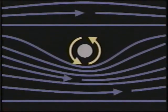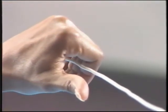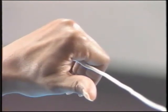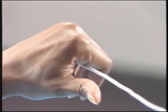The conductor's flux lines circle it in a specific way depending on the direction of current flow. Remember, the left-hand rule for conductors can be used to determine the direction of the flux lines. This rule will help you to visualize the direction of flux lines around the conductor. The key to the operation of an electric motor is found in the interaction of the two magnetic fields, the stationary field and the moving coil.